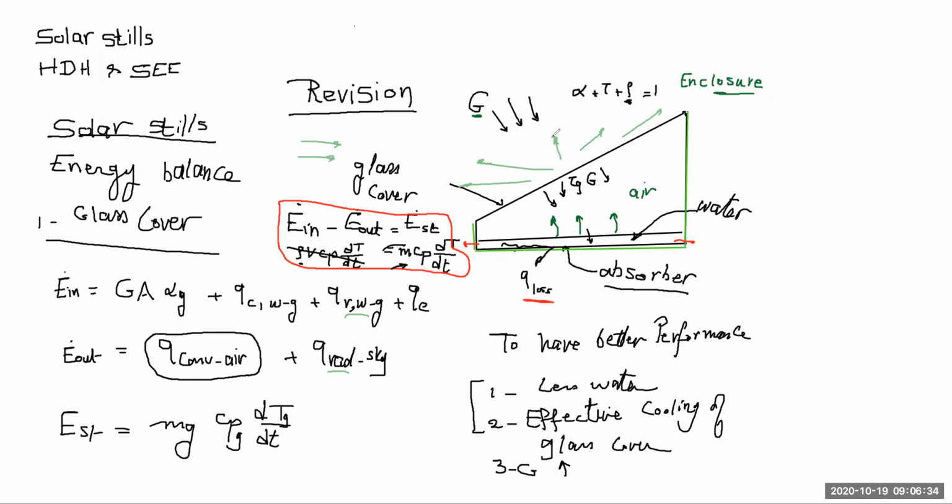There's an amount of energy coming here, and this amount is used to heat a small quantity of water. Suppose that I'm talking about the energy coming from the stove as Q, and Q is m Cp delta T. Then if the m is small, the delta T will be high. Accordingly, you can reach a higher temperature. Did I answer your question? Yes, thank you, Doctor. Okay, Abdullah?